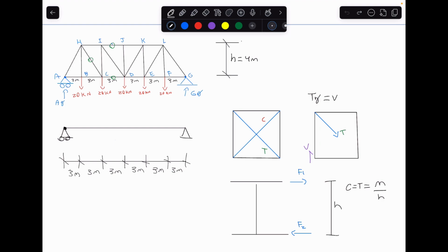We're going to use the bending moment diagrams and this equation right here in the bottom right to find the top and bottom chord forces. This basically just says, okay, so one of the chords is in compression and one's in tension, and to find the magnitudes of each chord, we're going to use the bending moment at that location and the truss height.